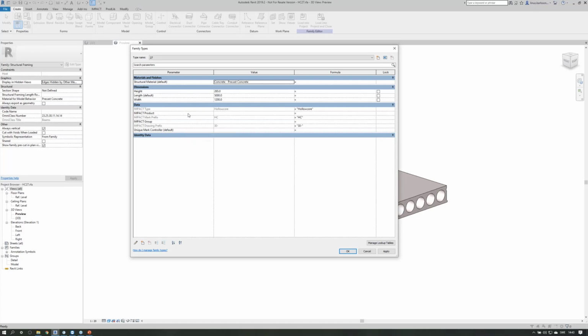And if you remember how it looked in the naming tab, most of them are according to that. So we have the drawing prefix, the element mark prefix, as you see here, the group and the product. And then we have one specific one that indicates what sort of element type it is. Here we need to specify if it's a holocore, a column, a beam and such.